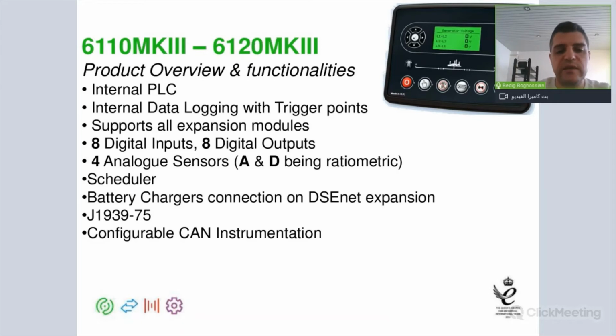Why did the temperature rise on the engine? Well, you can look at the graphs, and at the same time, you can look at the kilowatt level. Then you can know that because of high kilowatt levels, the engine temperature was rising, and you can show this to the operator or to your end customer.